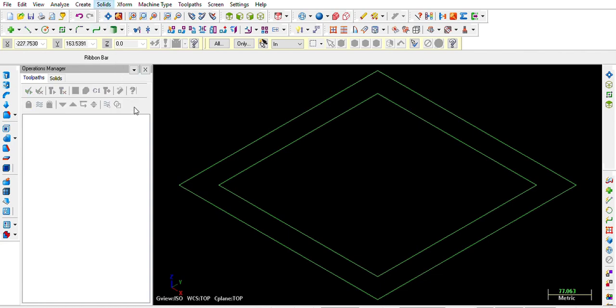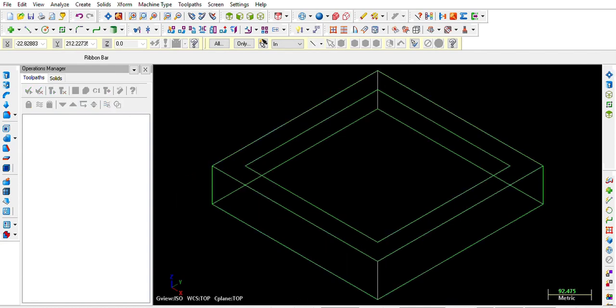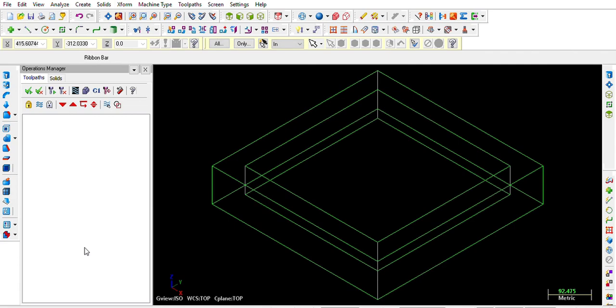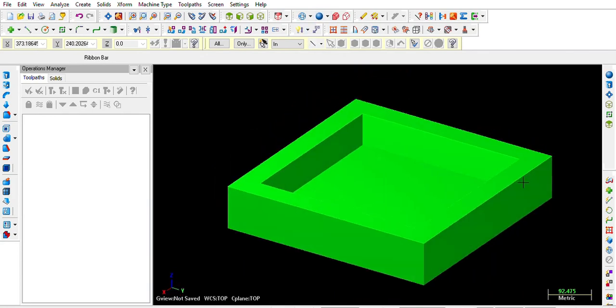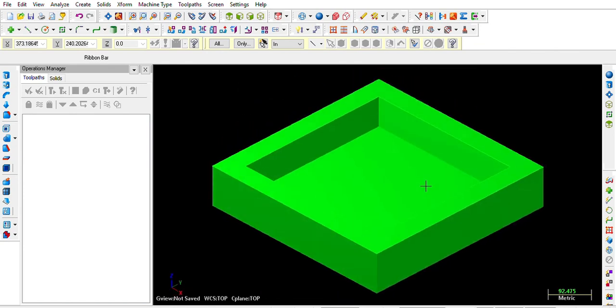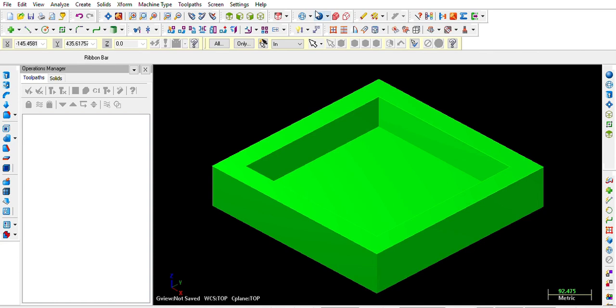Now I am going to use the solid extrude chain command, up to a distance of, let's say, 100 mm. This is the thickness, so this is the rectangular solid object. I need to cut this particular inside rectangle that has been drawn, or rather I would like to generate a pocket of 75 mm size. So this is the pocket. If you want to look into the three-dimensional profile of this, you can click this option to have a three-dimensional solid object pictured with surface. This is the wireframe model, this is the surface model, the shaded part, and this is the wire gradient part.